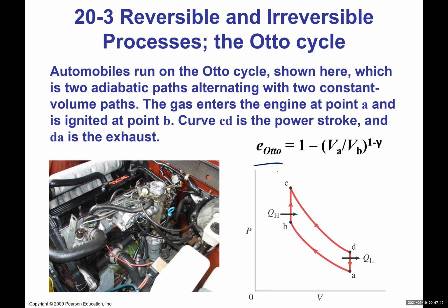Okay, so again, it's kind of similar to the Carnot engine in such a way that it's cyclic. So you start with A, then from A to B you have an adiabatic path. So there are no isothermal compressions or expansions here. You basically have adiabatic and isochoric or isovolumetric paths, where the heat is added or removed, because you need one process where the heat enters and another where heat is dumped. But here the difference is that let's call this path 1, it's adiabatic, which means there is no heat added or removed for this path. And path 3 is also adiabatic, where again no heat exchange occurs.